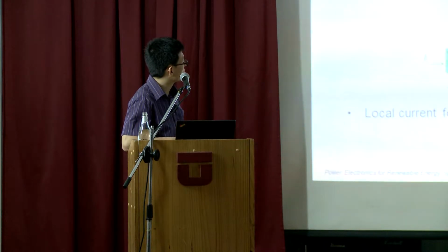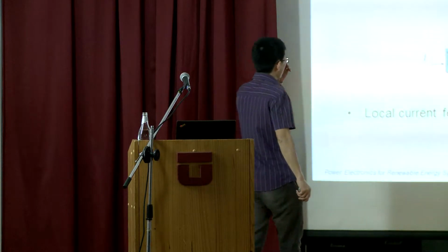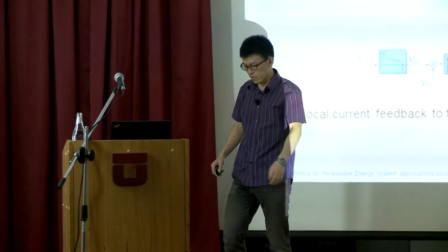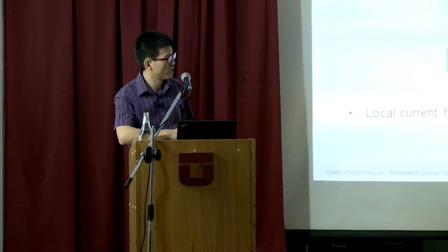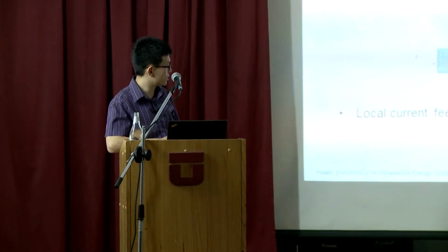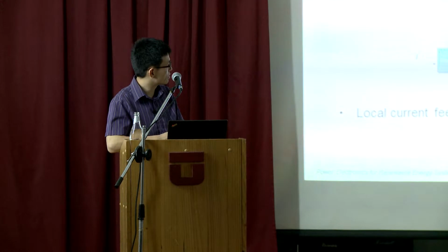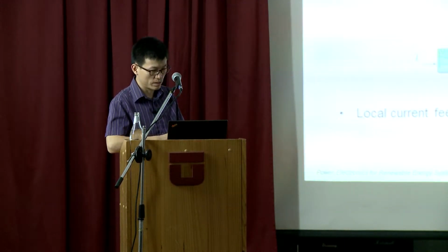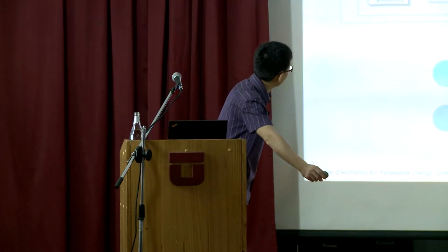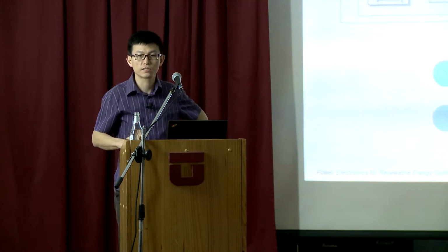For voltage mode, what you really find is current feedback. The current feedback is connected to the droop. So in this case, the voltage is the reference to the DC voltage controller. You see this is VDC. You have a local current feedback loop to the droop characteristic. So we connected this one. Simple. Yes, go on.